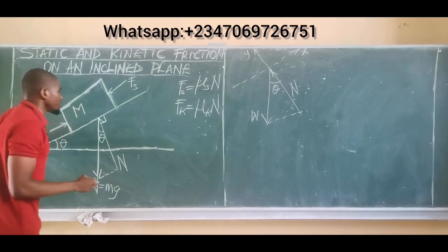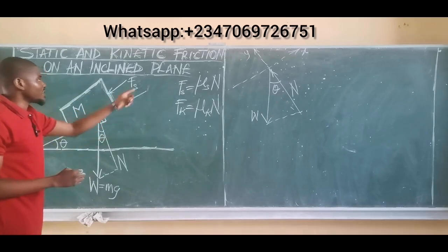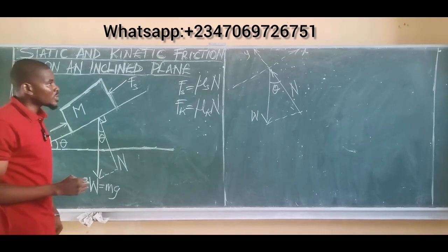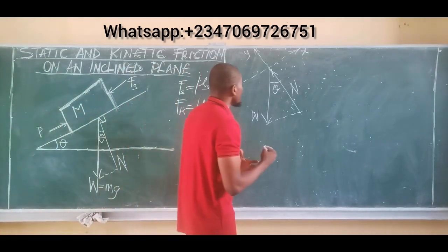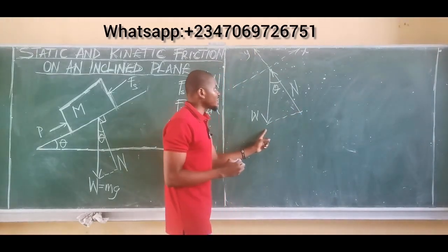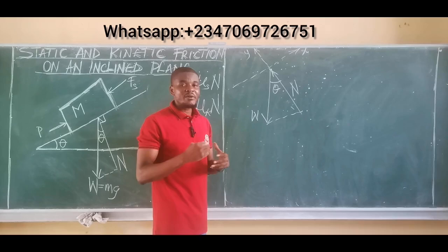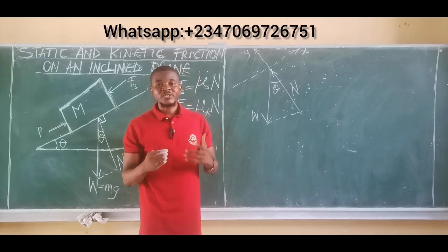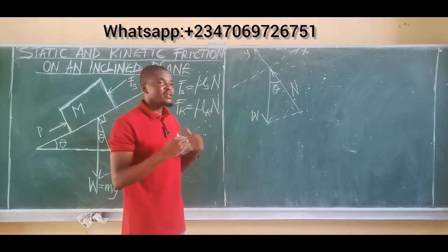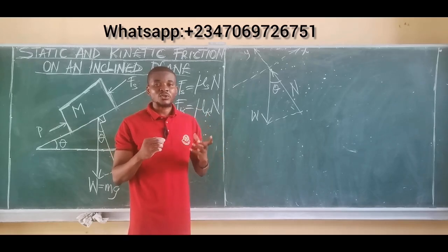So when motion is up the plane, it's purely horizontal, inclined horizontally, and when motion is down the plane, it is also horizontal but inclined horizontally downwards. Okay, so you observe that normal reaction is inclined vertically, but the weight is purely vertical, which means the weight now is acting as a two-dimensional force system, and as such, there is going to be a need to resolve the weight. Now, I always say in my 2D force videos, to resolve any component in any direction, all you